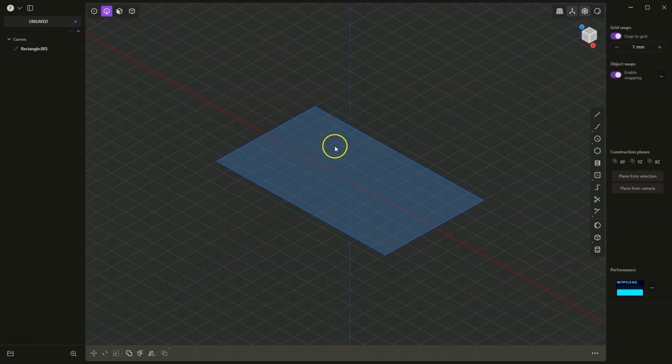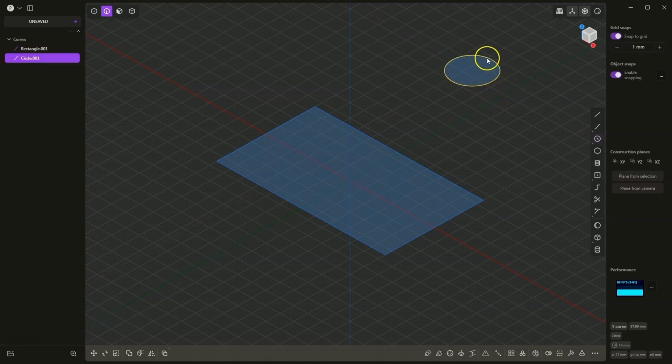We have drawn a rectangle, now we will create another shape. We will create a circle. Select Circle Drawing, and here, just like when drawing rectangles, when I press the left mouse button, several commands will appear. Let's choose the command to draw a circle from the center. Now, to draw such a circle, we simply define the center point and specify the second point of the circle. Here I drew an arbitrary circle, so I'll press the Delete key to remove it.